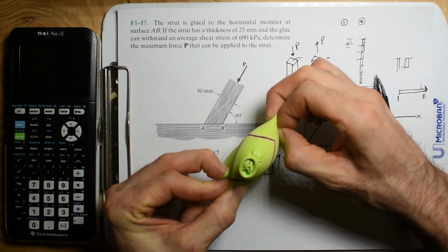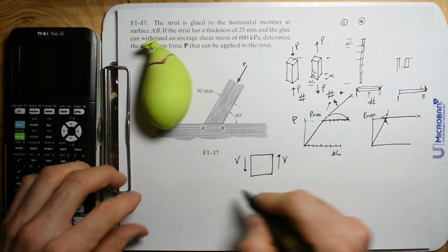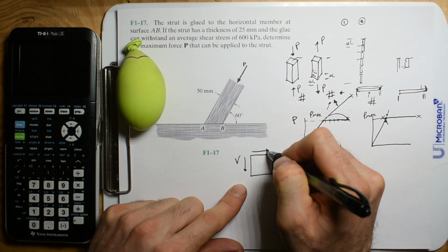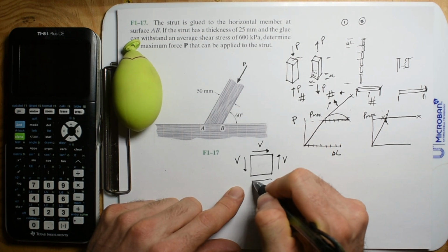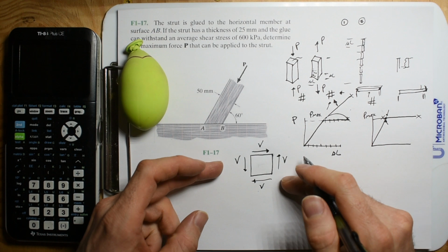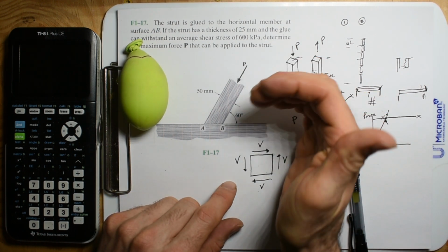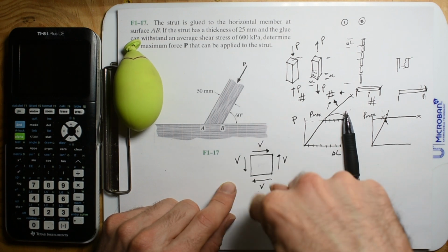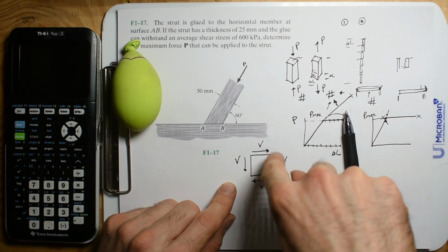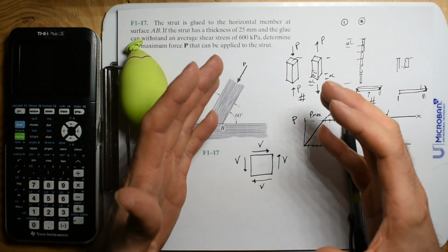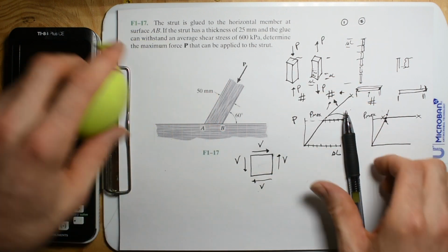And what happens is that you get this shape to form. You have to have this force and this force, and they're equal. Those are your shear forces. These two make a moment going that way, kind of a torque that in dynamics would cause a rotation. These two forces counter that, and those two torques, those moments, balance.